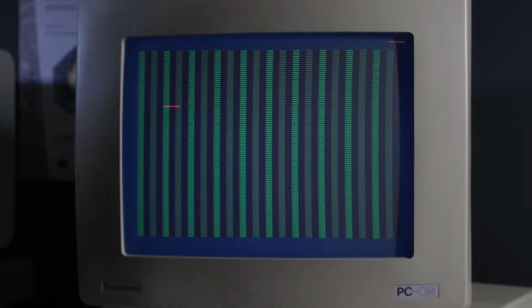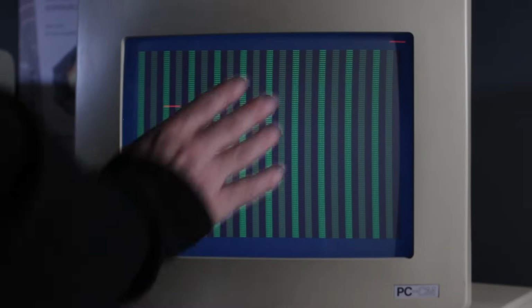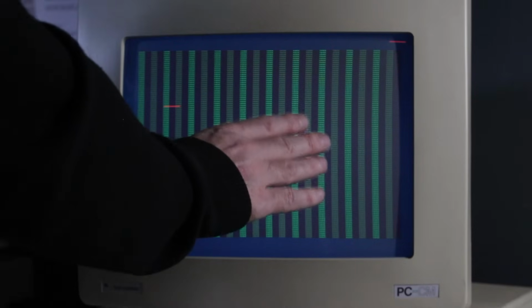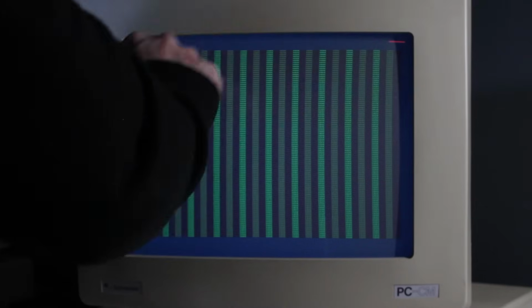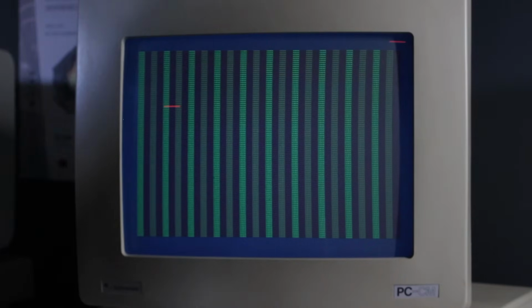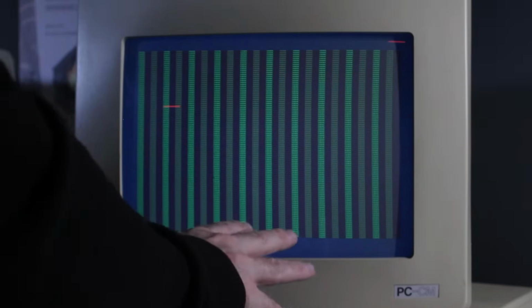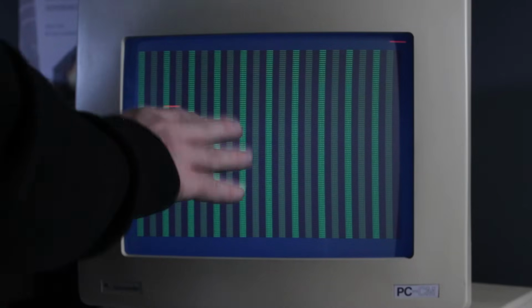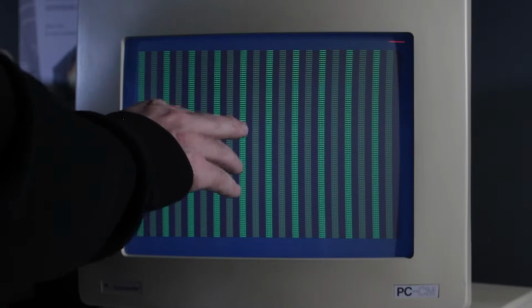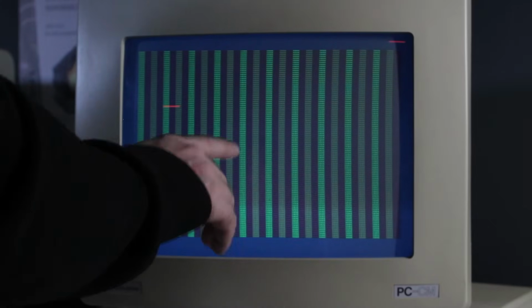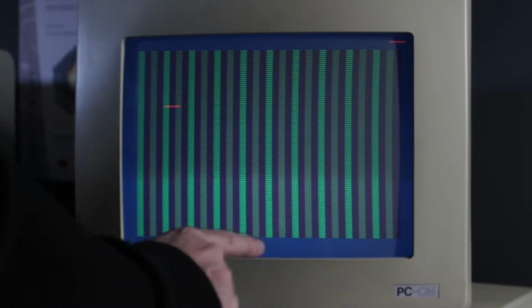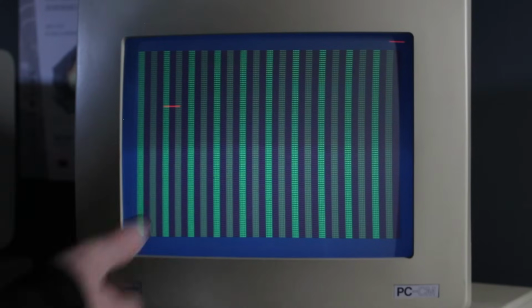Now, of course, I had to do a lot of things to get it to this point. First of all, I had to turn DRAM refresh off. You can't use the DMA controller for that. It fires really often, and this just interferes with everything. So that's off. And to prevent parity errors, obviously I have to do DRAM refresh manually using the trick I explained earlier, executing code in every segment of RAM, which charges up those little capacitors and stops you from losing the RAM contents.